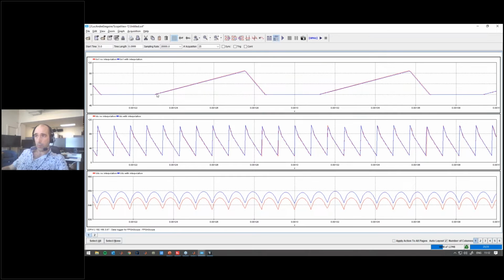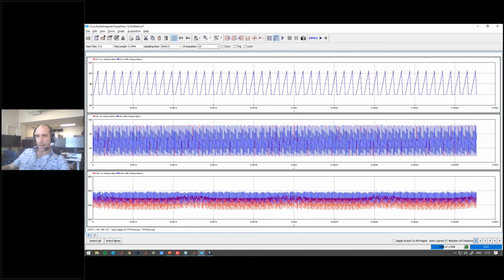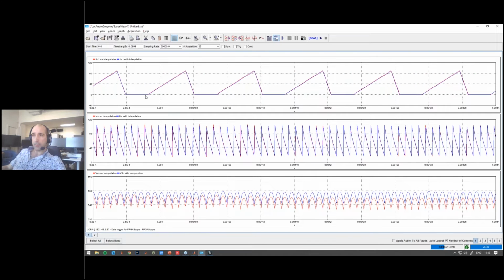And if you look at one single phase current, you can see that the result is not, yeah, maybe I should have explained to you first the different signals. So first here we have the current from one leg. Here we have the DC current, so the sum of all the legs on the DC side, and then we have the DC voltage. So the aliasing that we were seeing and the oscillation that we were observing was on the DC bus, so on the DC voltage. And what I would like to point out is that the error on the current is hardly noticeable.